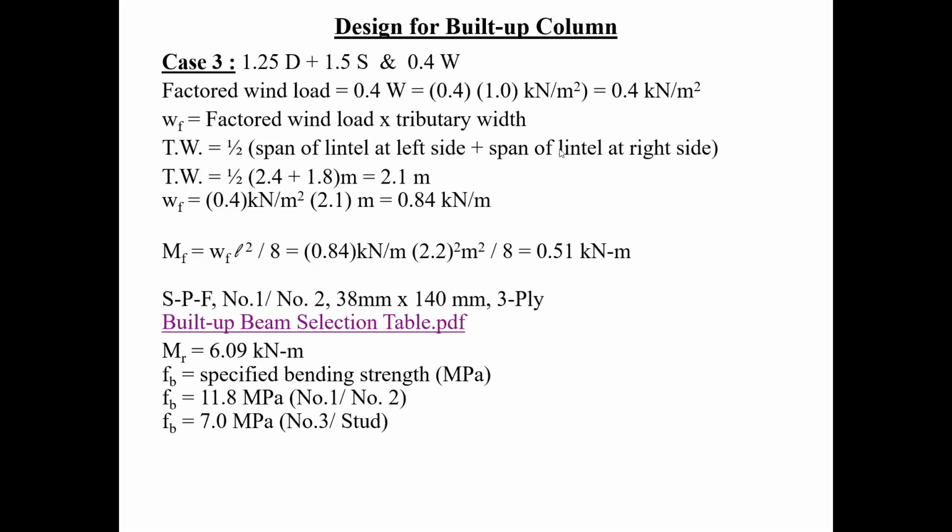So now, all I have to do is this: this value here was calculated with this value here. So if I divide by that value, I remove the number 1, number 2, and if I multiply by this value, I'm going to be bringing it up to a number 3. In other words, I adjust the value from the table to represent this bending strength here.